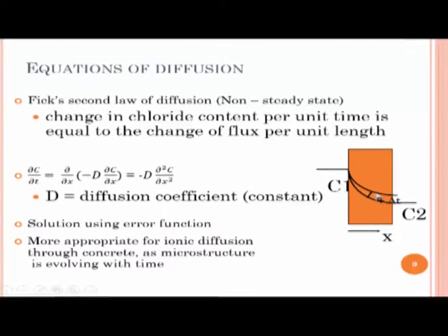If you change your time a little bit, what is going to happen? The concentration outside remains C1 because, for example, seawater will have a constant concentration all the time. What is inside the concrete would now change, okay. C2 will have changed now to a different level.